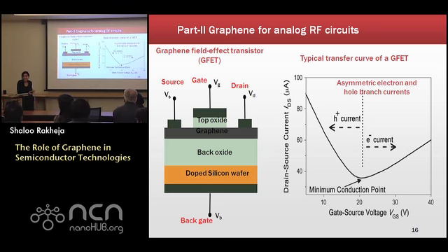May as well get all of the questions about interconnects out of the way here before you go on to transistors. So help me. I think your conclusion is graphene could be better than copper for energy. Okay. And if I understand correctly, it's not because of sheet resistance, it's because of capacitance. Is that right? Graphene can be better. Capacitance, why is it lower than copper? Is it because it's thin? Thin. Okay, so there's less of a sidewall.